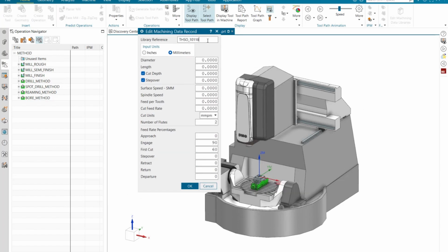and we can go ahead and insert a machining record. So for the library reference, let's give a unique name. So we are saying it's finish with titanium 6 and using titanium carbonitride coated carbide end mill. Okay, and let's say I have a proven feeds and speeds for a specific diameter cutter using these two filters, one with the part material and one with the tool material.